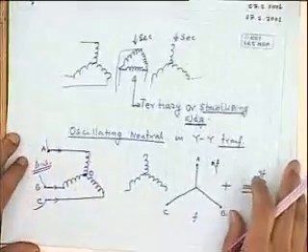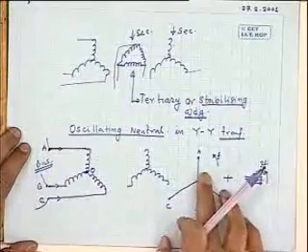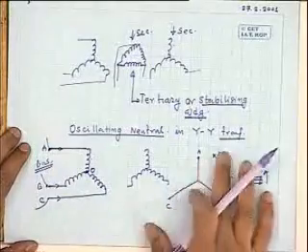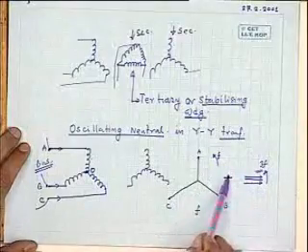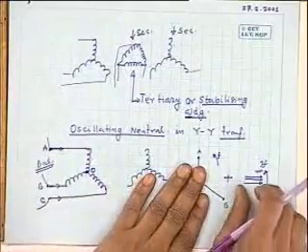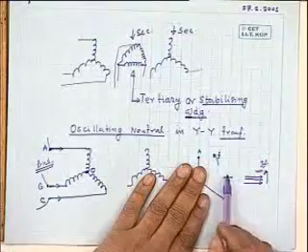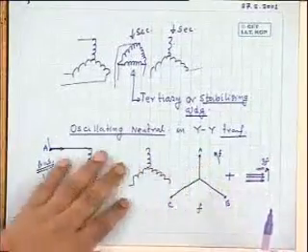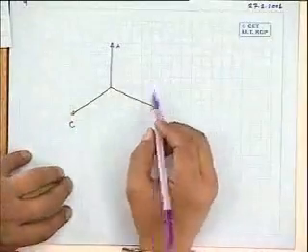And as you can see, to draw a phasor diagram on a plane, all the phasors should be of the same frequency. Then only you can represent them relatively. Now, how can these phasors be summed up? You consider this to be stationary and this to be moving with a relative speed of twice f. This way one can represent it.